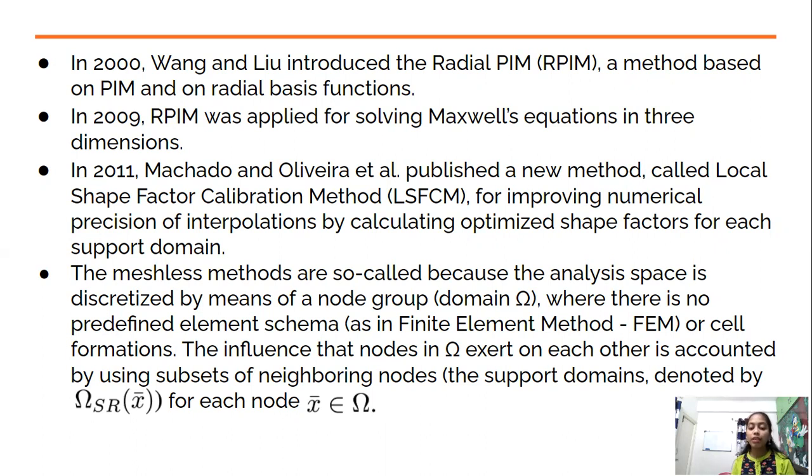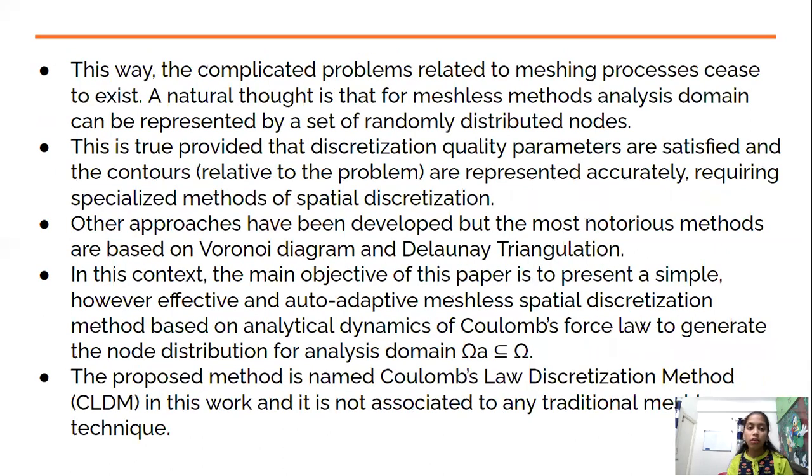The influence that the nodes exert on each other is accounted for by using a subset of neighboring nodes, the support domain, denoted for each node x bar. This way, the complicated problems related to the meshing process cease to exist. A natural thought is that for meshless method analysis, the domain can be represented by a set of randomly distributed nodes.